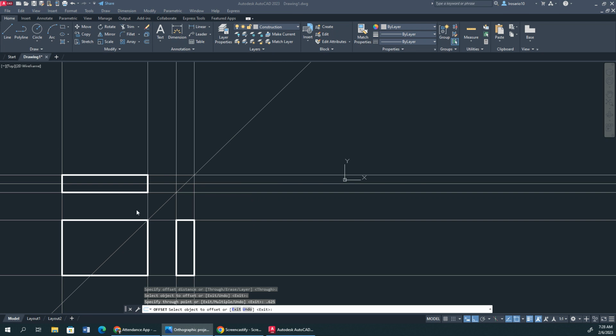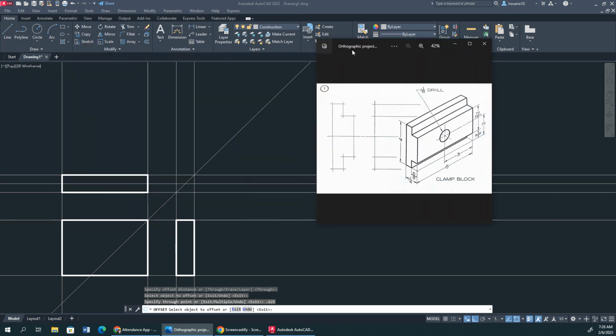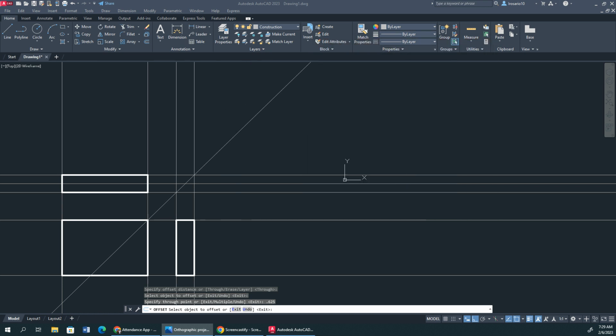Now, that's that. We also have to make sure we offset our lines for the circle. So if we know our center line is 3 inches from the edge, our circle is 1 1/8. 1 1/8 translates to 1.125 in decimal form. Divided by 2, that's 0.5625. Now remember those numbers, okay?